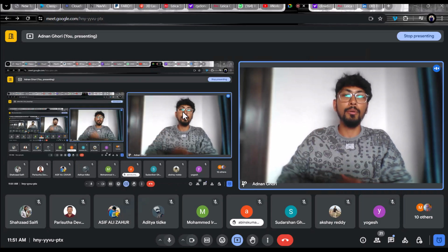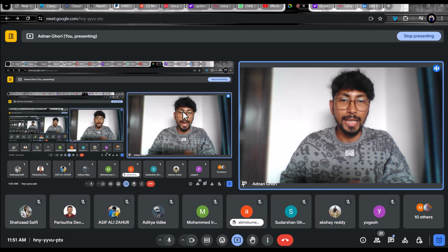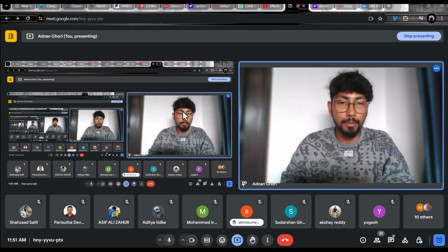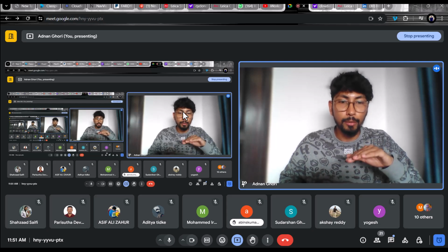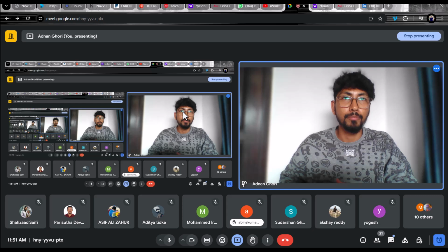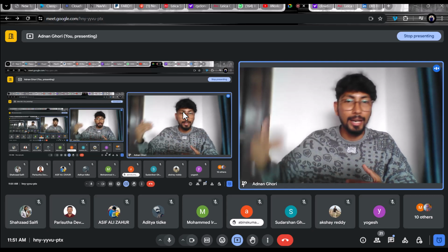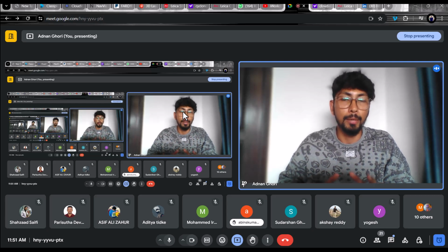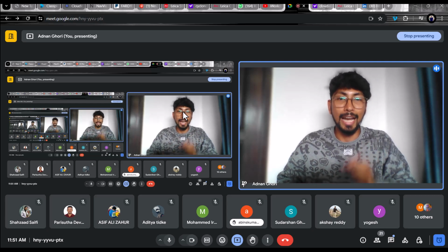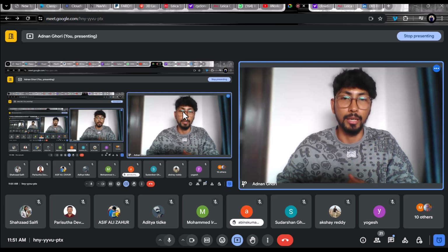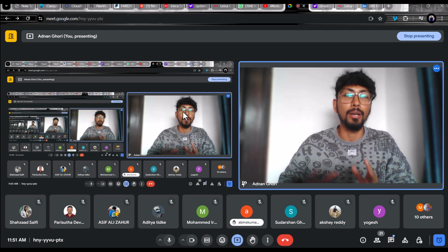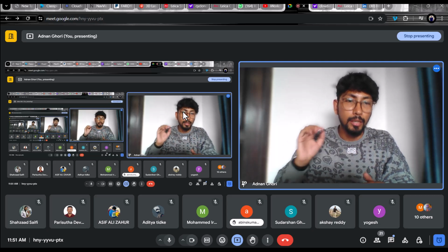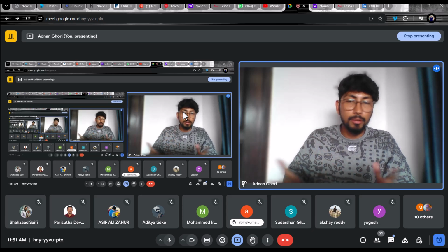Second, you need to know how to work in a 3D coordinate system, X, Y and Z. Basically, when you work on a simple Revit project, you work in a 2D environment, or you work in a south elevation, north elevation, or different elevations or sections, right? But you mostly don't work in a 3D environment for the modeling part in Revit. But with scan to BIM, you need to work in a 3D environment mostly. It's like working in all three coordinate systems. You need to arrange the model from one level, then you need to arrange the model from the front elevation as well. So these kind of things you need to know.